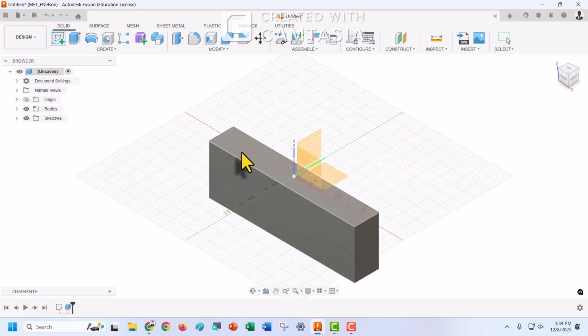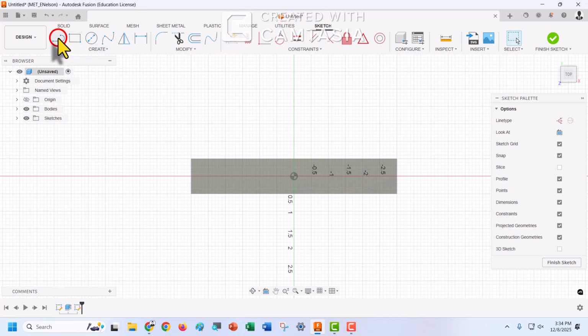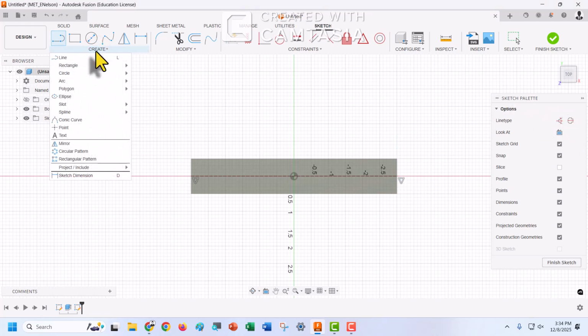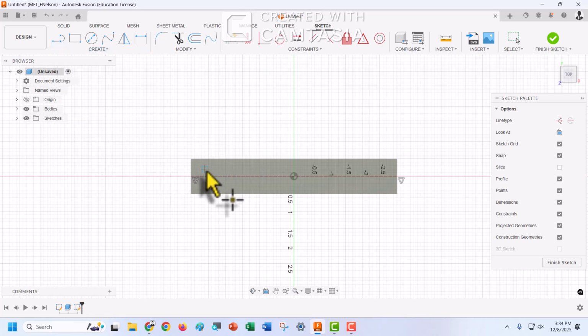Create sketch. Choose this plane, the top face. Go to line and choose construction. Go right to the x-axis, that should be a midpoint, and all the way across to the other midpoint. Turn off your line type as a construction. Now go back to point, and what I want are 3 arbitrary points left of the origin and 3 arbitrary points to the right of the origin.